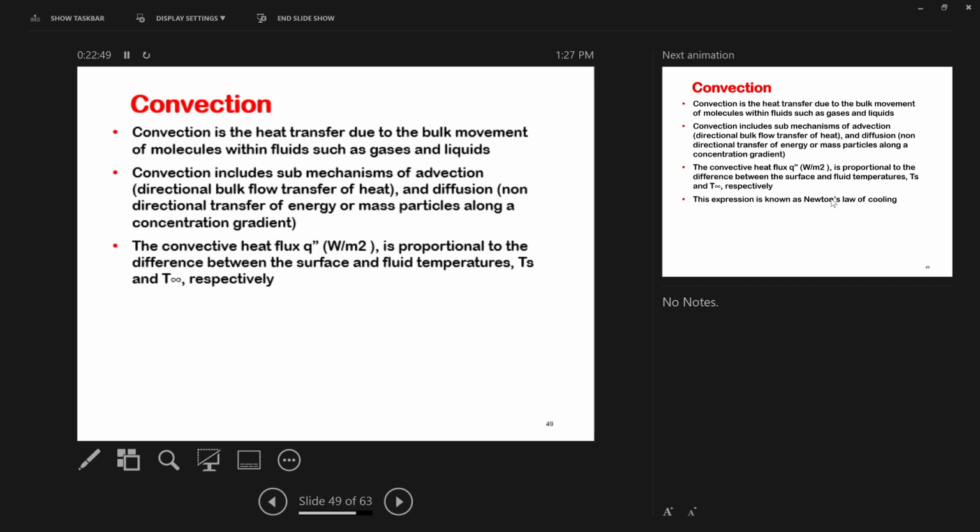Okay. So for convection, instead of having a conductivity, we are going to have a convective heat transfer coefficient. The difference between a convective heat transfer coefficient, which we denote with H, and conductivity is that conductivity is a material property. Like the conductivity of wood is different from a plastic, is different from composite, and composite has different conductivities in different directions, but it is still a material property, right? The conductivity of steel, and we usually assume that it is independent of the temperature, right?